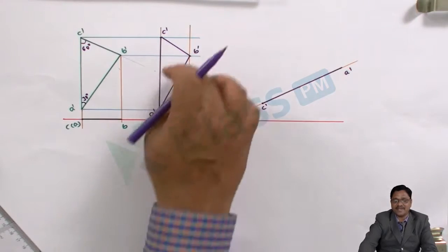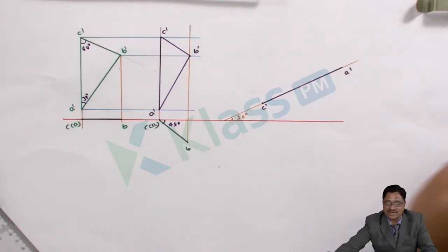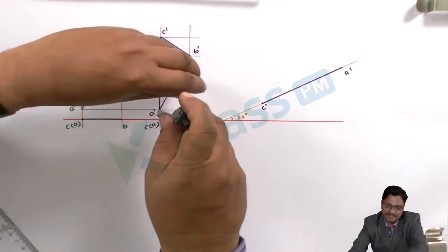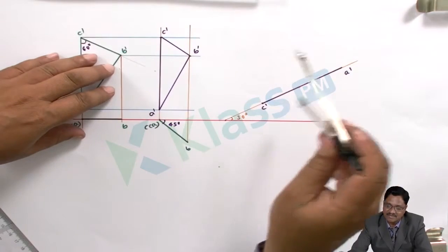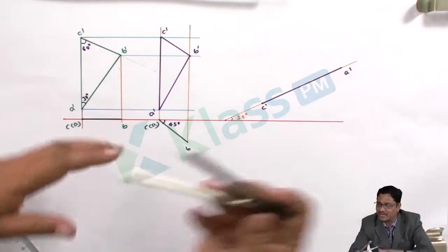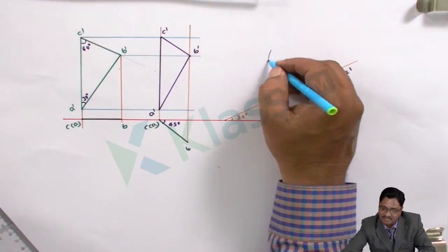So for that, when we have a common point, the compass is the better instrument. So take the compass, measure the distance from A to B. The same, where is the A point? Here is the A point. We can just draw the arc. Okay, you cannot see that impression, so I am taking that impression off here.